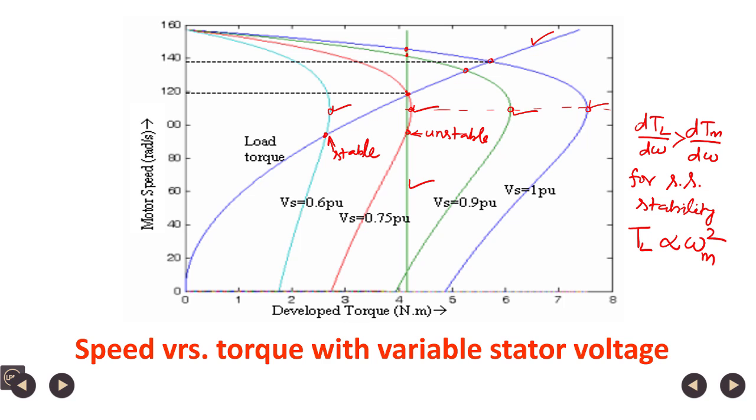So, for this second type of load, for which load torque is proportional to the square of the speed, for example fan, pump, compressor, propellers, speed can be reduced from the maximum speed down to 0 speed. Speed control is possible. So, the range of speed control is wide with fan and pump type of loads, but for constant torque load the minimum speed is given by this line, corresponding to maximum torque, at which maximum torque is obtained here. This is the minimum speed.